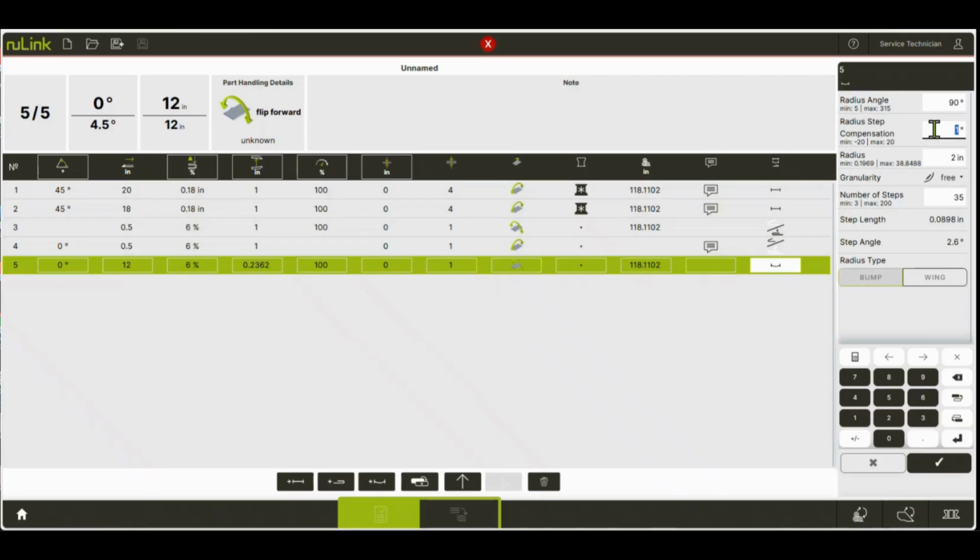So let's just say I need 5 degrees. So what's going to happen when I set up for this, it's going to take that 2.6 degree, which is my theoretical and my expected result. It's going to add 5 degrees to it. So I'm going to actually bend to 7.6 degrees. Okay. So now we're ready to go start bending.